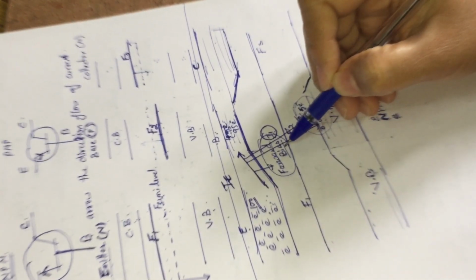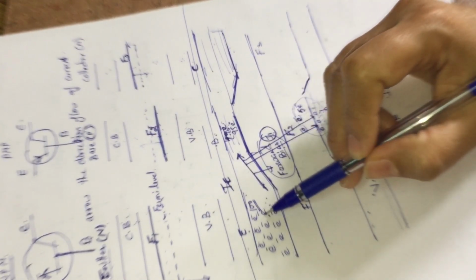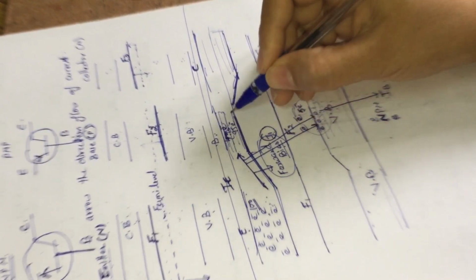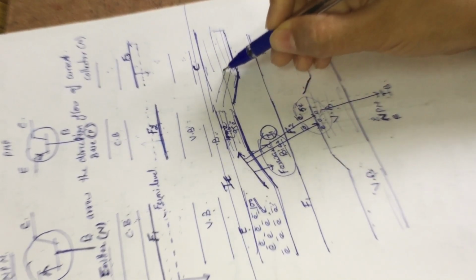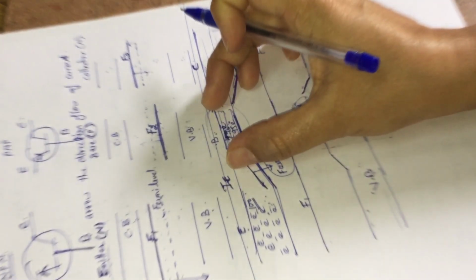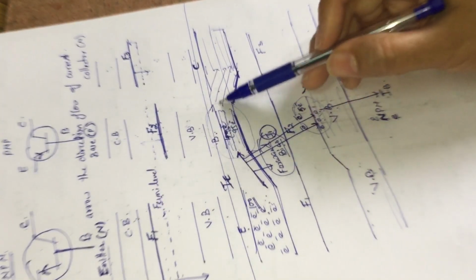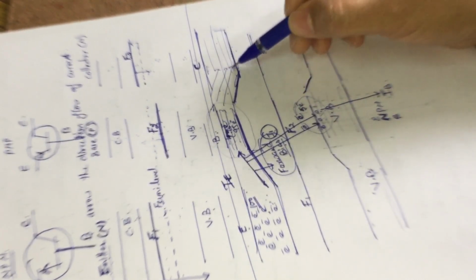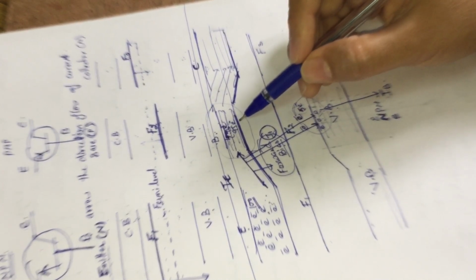As forward biasing gives sufficient energy so that electrons from the emitter region move towards the base region and gain sufficient kinetic energy, they can easily move towards our collector region, because the length of diffusion is very small, as the base region is very narrow. Electrons can easily move towards the collector region as the energy of the collector conduction band is small compared to the conduction band of our base region.